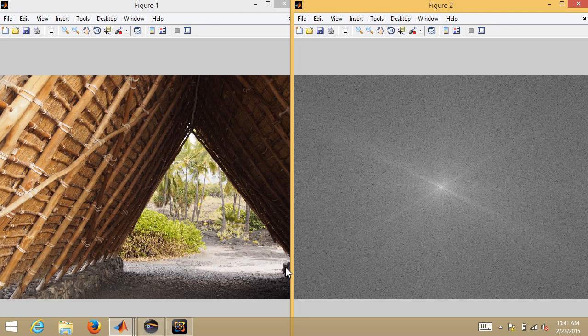Yeah, question? So for the FFT, you said if you didn't shift it, you would start from low to high and then go back to low. That's right. Then could you just take a quadrant? And is it the same thing? Yeah, that's a good point. So could you just take a quadrant of the FFT and get what you wanted from symmetry properties? Right. Short answer is yes. You don't actually have to view the whole thing because there's always going to be this symmetry. And yeah, I think you could think about it like looking at a quadrant.